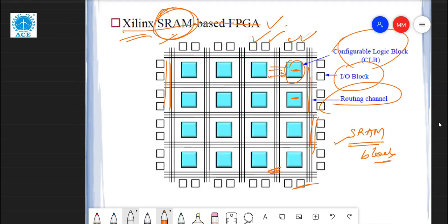So this is the concept of field programmable gate arrays, a wonderful concept. In FPGAs all blocks are programmed in the design, and n number of blocks are present. Major blocks are configurable logic blocks, IO blocks, routing channels, SRAM blocks, logic gates, muxes, and flip flops. All these blocks are programmed in this case.